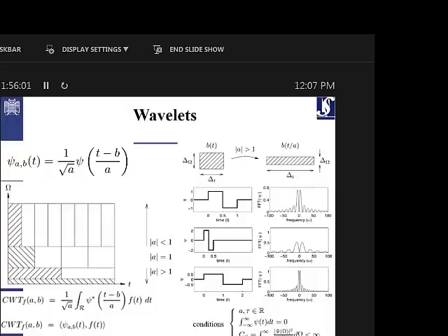If you remove the ambiguity, you will get some number, and it will not be infinity. The same thing for the higher frequencies, omega infinity over infinity, for example. If you have an ambiguous part, you can remove the ambiguity and you'll get some number. But in the other case, you will get infinity, and this will not hold. That's why this condition represents that the mother wavelet should be a band pass filter.